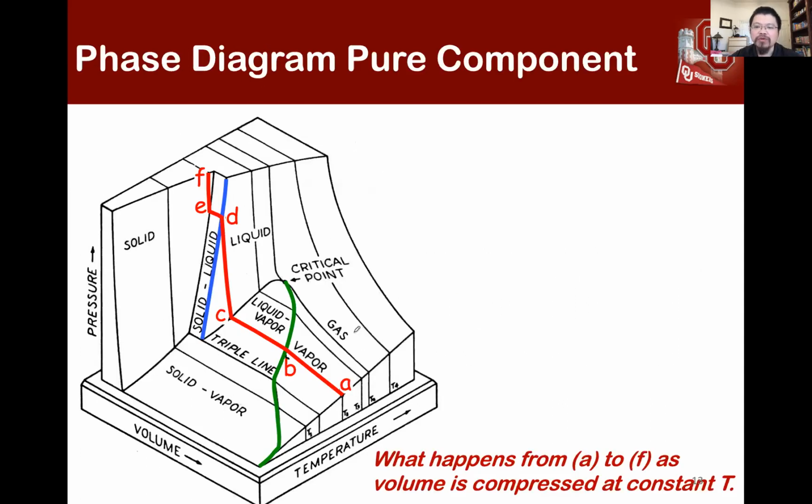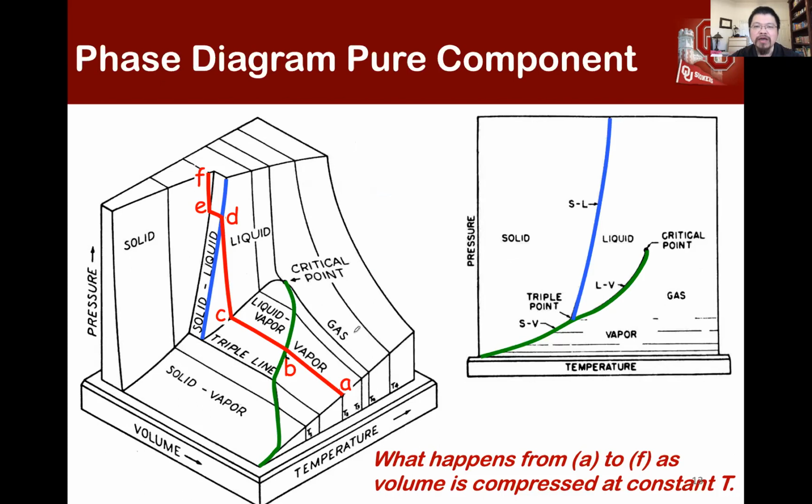So here is a quick review on the phase equilibrium. If we start with the phase diagram, let's stick with the point A, where according to the diagram, we are in the vapor phase, right? If you try to maintain the fixed temperature, that would be the isothermal processes. If we are going to maintain the temperature, but we try to do some driving force manipulation, then we are able to push the superheated vapor into the liquid vapor equilibrium at B.